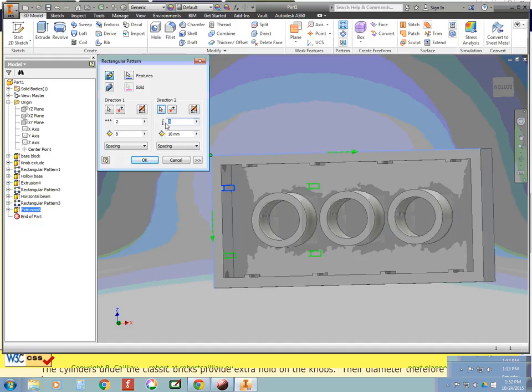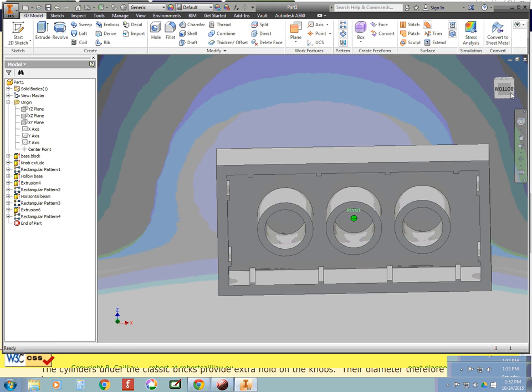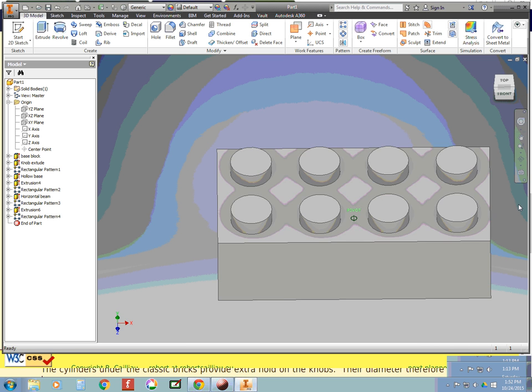So let's take a look at that. Whoops, we got 2. Make this 31.8 minus 1.2 for one wall thickness, minus 1.2 for the other wall thickness, minus 0.3 for the thickness of that extruded feature of the beam. I click on OK, and my Lego brick is done.